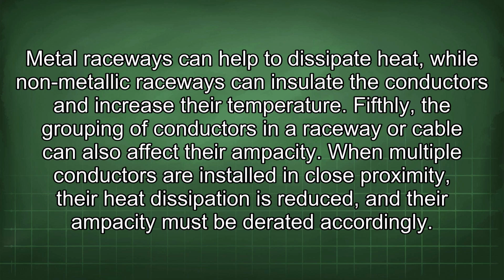Fifthly, the grouping of conductors in a raceway or cable can also affect their ampacity. When multiple conductors are installed in close proximity, their heat dissipation is reduced, and their ampacity must be derated accordingly.